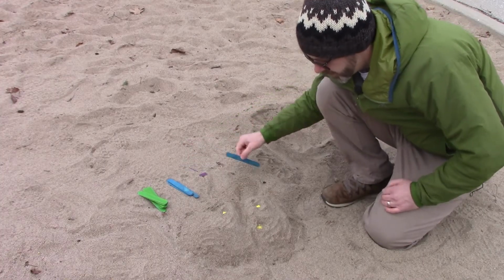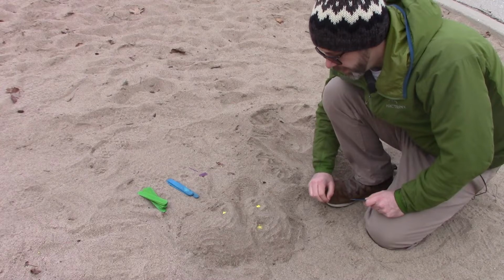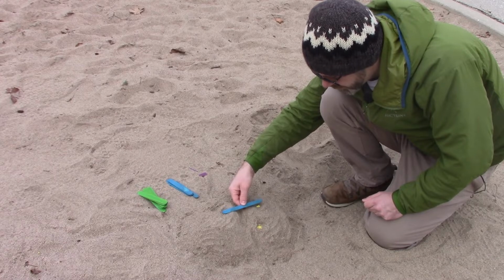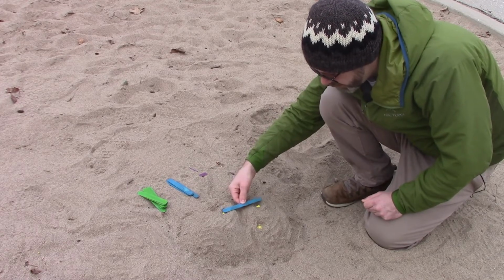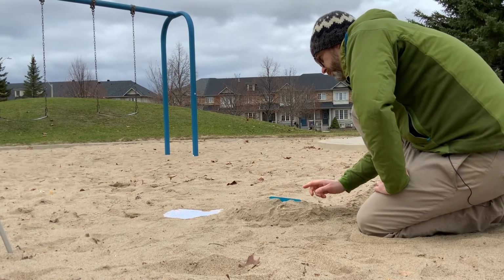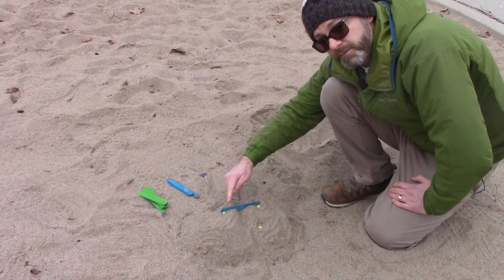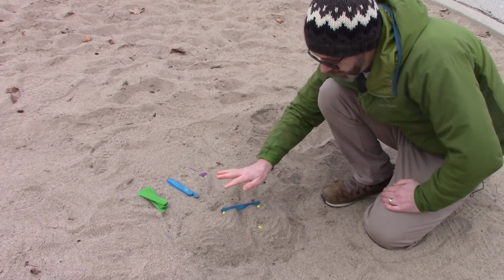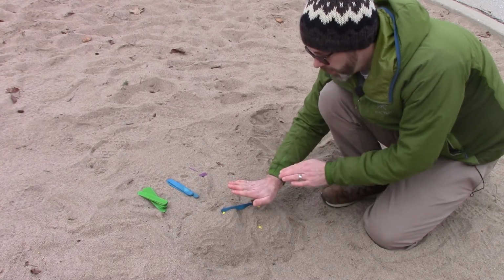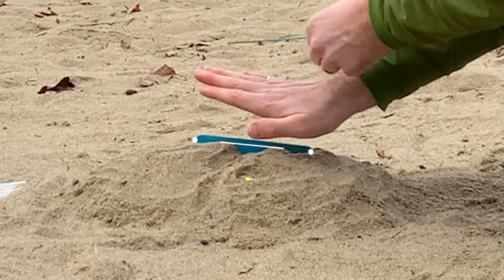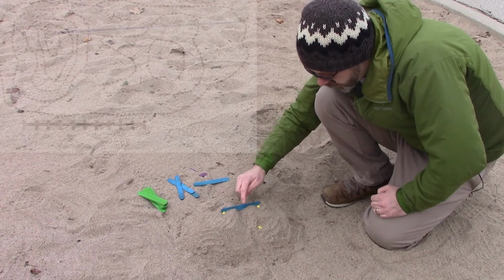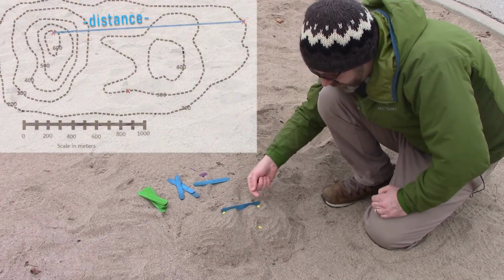The first step is to connect 2 of the points together, and we know the horizontal distance in space between those 2 points. All right, we need to determine the length of this line, and we know that the plane exists on that line at some angle, and we can calculate the angle from the horizontal, the blue line, down to the plane. In order to do that, we know the horizontal distance along the map.